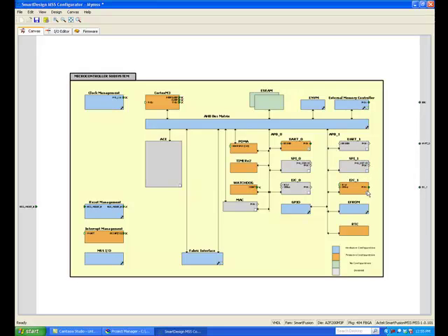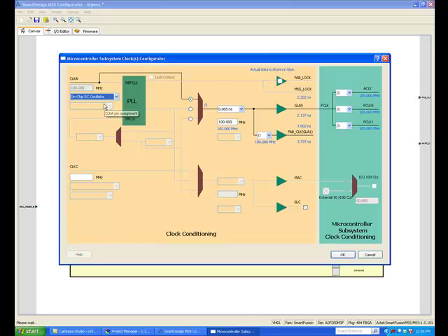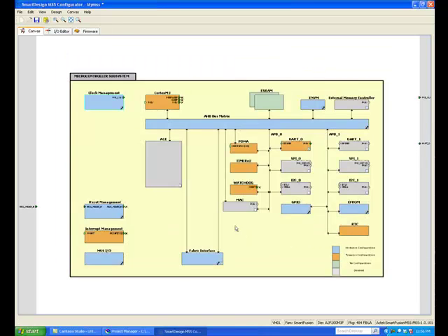When using the fabric, you need to connect the fabric clock pin of the clock management block by right-clicking the fab_clock pin and selecting Clear Attribute. Then right-click again on the fab clock pin and select Promote to Top Level. Double-click the clock management block to view the possible configurations, but for this design we will accept the configurator default settings. Click OK when finished.